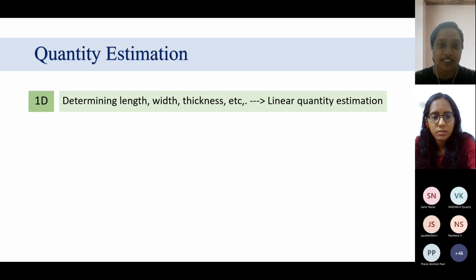But in other terms, when we are trying to collect the estimate from a contractor who would be constructing the pile in site, they would go with the term running meters. That is the length or depth of the pile. That is the instance where you are using length over the volume.